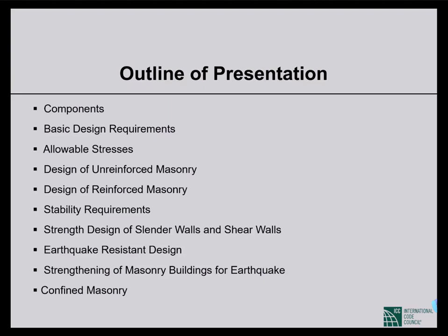However, for earthquake loading, the total base shear is divided among the walls based on their shear stiffness, which is actually based on the effective area. So based on the effective area, we distribute the shear force onto the walls.